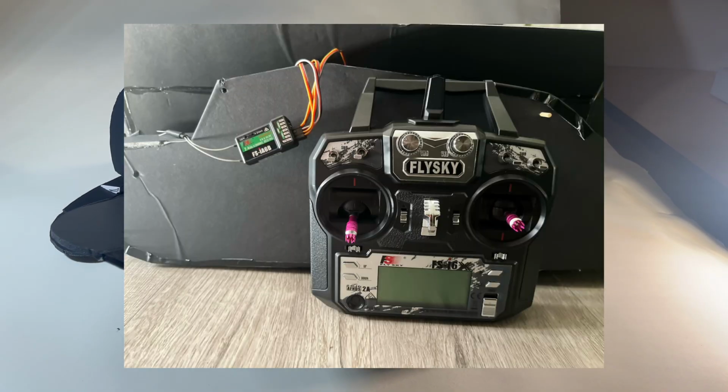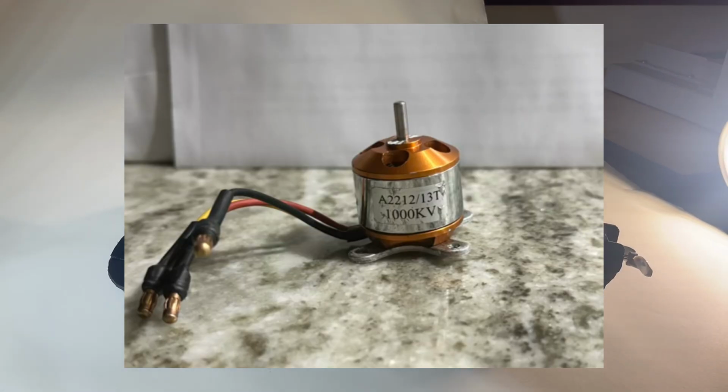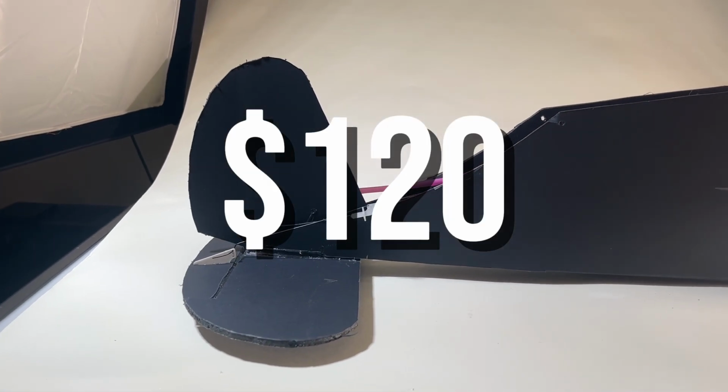We used a FlySky transmitter and receiver, an 11.1 volt LiPo battery, an ESC, a brushless motor, and 2 servos, one for the elevator and one for the rudder, connected through the receiver with push rods and control horns. Our electronic total cost was around $120.